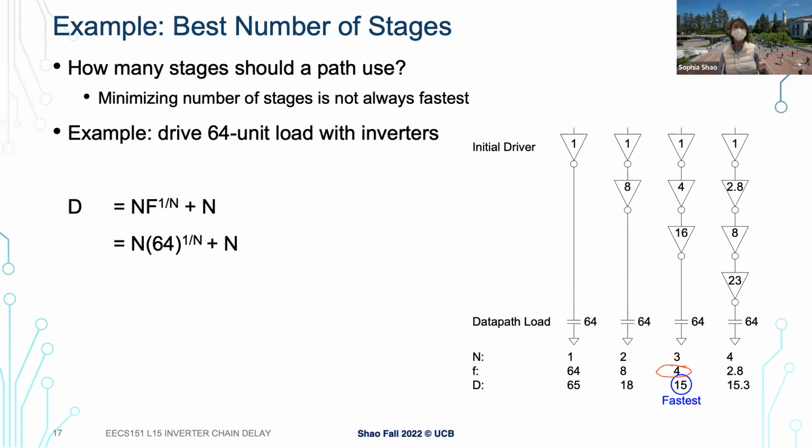Well, it's still very important, but when people discuss delay in circuit design, a lot of the time they're basically expressing delay as a multiple of fan out of 4, or FO4. This becomes a constant because typically when we think about the stages, if each stage is driving 4, with the effort fan out of 4, it is typically more balanced. So a fan out of 4 is also a very commonly used metric in the design.